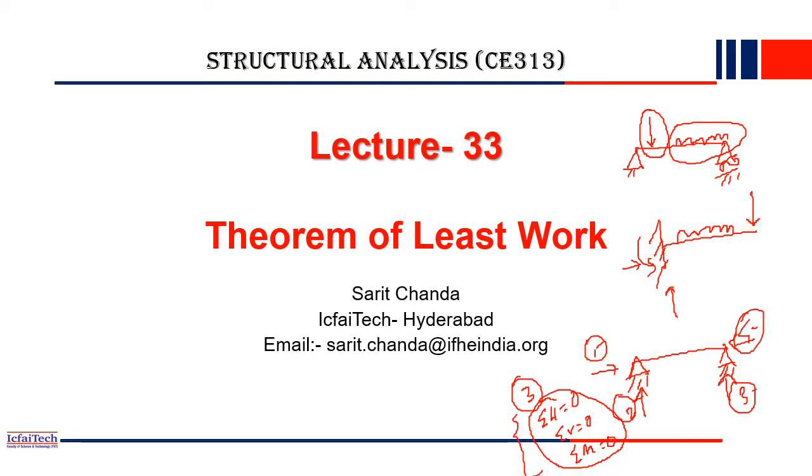So in that case, we have to use this method, that is the theorem of least work method, to calculate the reactions and the other forces also. So 3 values we can get using these 3 equations, but one will be unknown, that we can't get. So that can be solved using the theorem of least work.